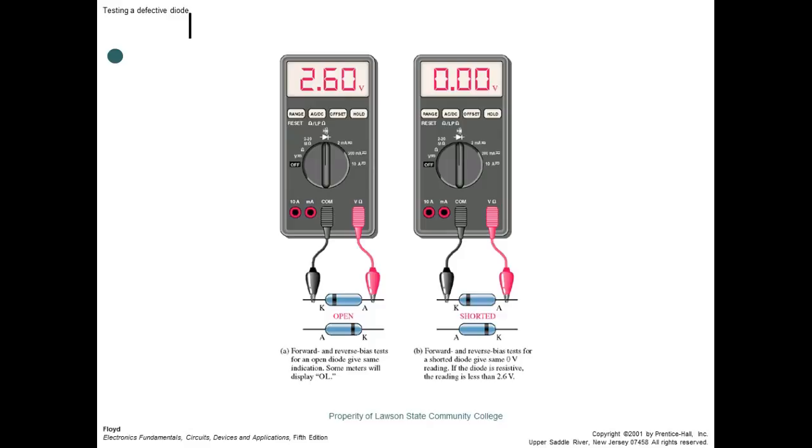The number 4 galvanizing line at US Steel had DC cranes, and they used diodes to get the 250 volts. And you went into those diodes, and they were just hundreds of diodes in series with each other. And why? Well, not to drop the voltage, to prevent them from breaking over.